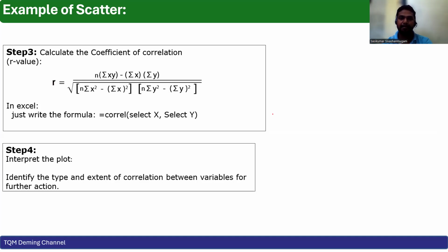So ultimately, the scatter diagram is very useful not only for problem solving. For any kind of data, for example, if you are doing a why-why analysis on a machine and you suspect the reason for varying dimensions, noise or frequent bearing failure, you can look at the oil lubricant value or oil temperature.